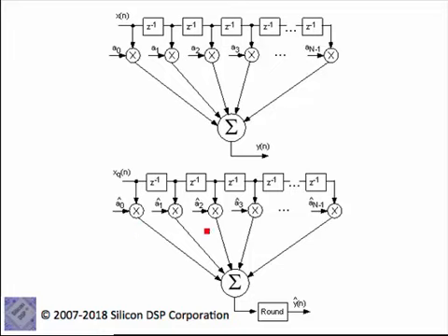In Capsim, we have blocks to perform the multiplication, or in the case of the blocks, subroutines that perform the multiplication. We specify the floating point coefficient and the number of fractional bits and the word size, and the subroutine will produce an output. The output size will be twice the size of the input register. So if the word length here, for example, is 16 bits and the word length here is 16 bits, then you get a 32-bit result.